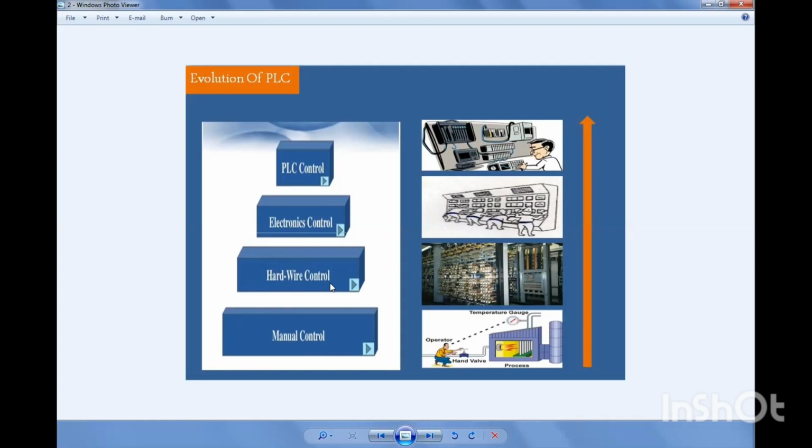One of the main disadvantages here is that it is really tough to find where the fault occurs. For example, in a simple control system, if there is one error in the wiring, it's really hard to find because we are dealing with thousands of wires. There is one saying in the control industry about the relay control system: if a fault happens, it is 5 hours to find the fault and 5 minutes to fix it. That is one of the main disadvantages of the hardware control system.